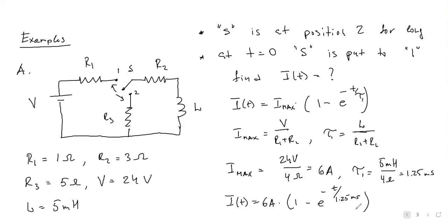Let's look back at this diagram. What will be the time constant when you switch it to position 2? The time constant. L over R, R3. L over R, accepted. What kind of resistance? Oh, is it R2 and R3? You mean plus? Yeah, they are connected in series again. R2 plus R3 would be the equivalent resistance, and inductance will discharge through the R3 plus R2.